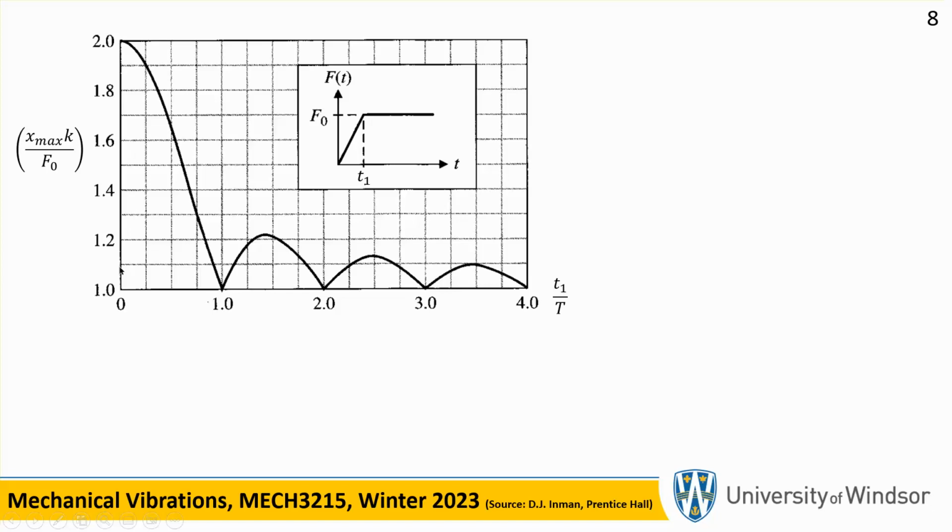You can see that. When it's a suddenly applied load, you drop the hammer, T1 is essentially zero. So you're at that location, and the block feels double the weight of the hammer, essentially.